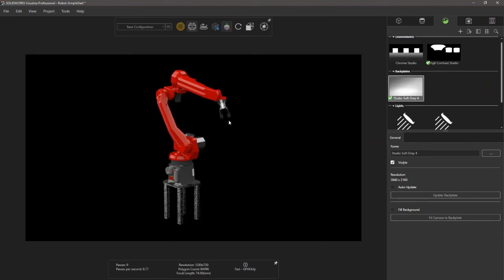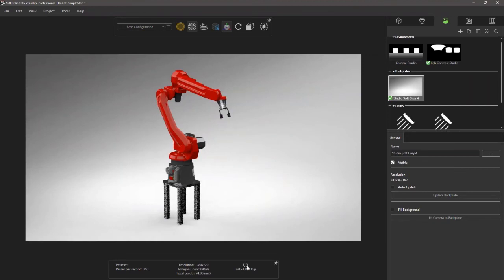Okay. I'm using also the new denoiser here. This is a new option. This works great. If I turn off this denoiser, this makes it render so much faster. You'll see how grainy the legs look. For instance, when I rotate, there's a graininess because the brush material takes a while to resolve, many render passes. And when I turn on the denoiser, it just skips that process. It's pretty amazing what it's doing. So you can get really nice renders with a lot less number of passes by turning on this denoiser. Okay. So that's a general idea.